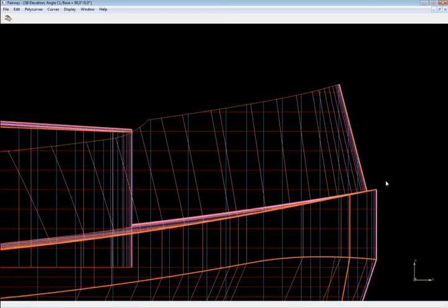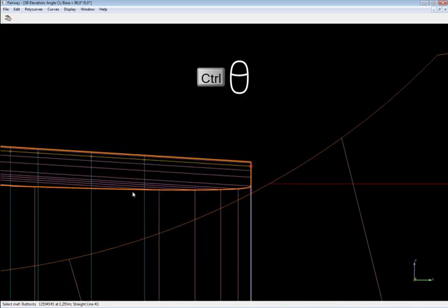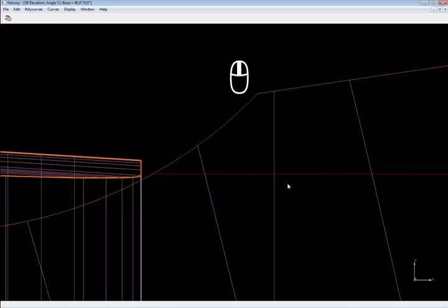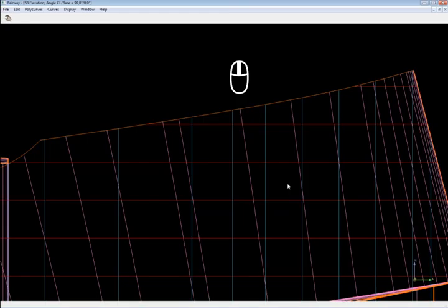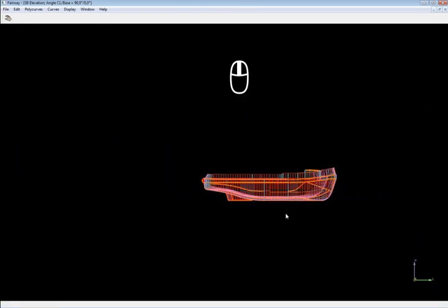Once you have obtained the basic manipulation skills, be sure to try the following two tricks because they often come in very handy. Firstly, you can zoom in on a single curve by zoom clicking on it. It goes like this: hold down the control key and click with the middle mouse button, or hold down the middle mouse button and click with the right mouse button. If you do the same on the background, you will zoom out or in so the whole model fills the screen. That's the second trick.